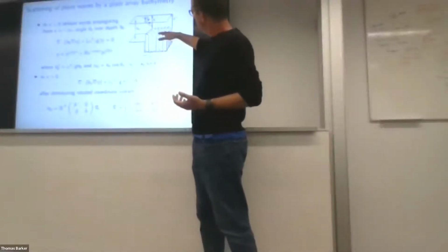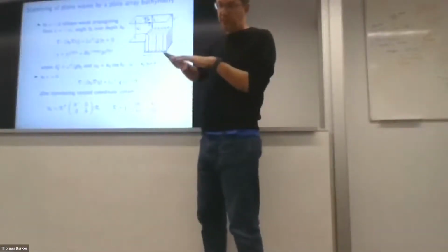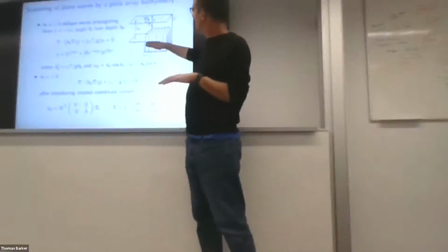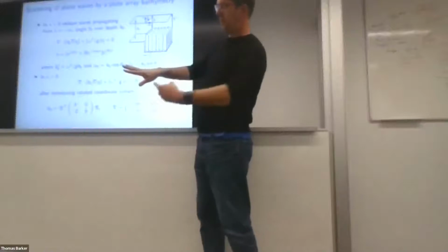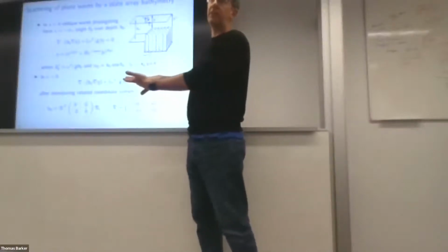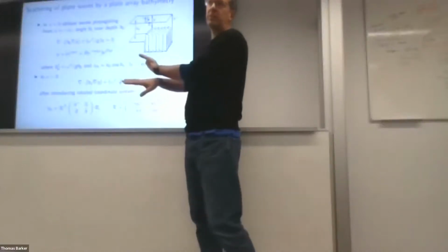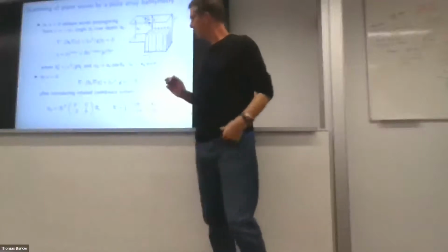I can also drop the H minus down to the level of H naught, so I can still have this pit, but I can drop the level down, and then if I've got waves coming in this direction, it's like riding a bike over a cattle grid, right? You don't drop down the slots, you just ride over the top, and again, you'll just get perfect transmission. So there are these kind of special cases.